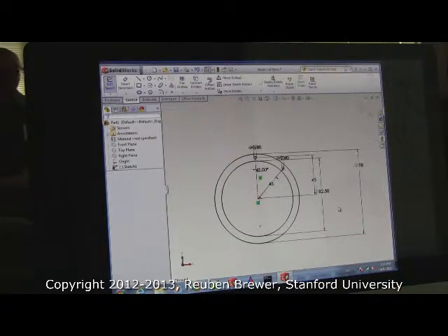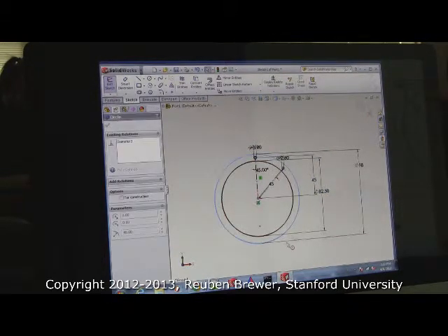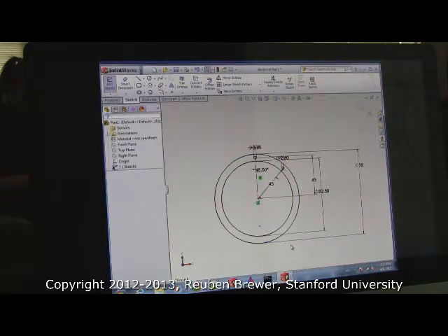So basically I'm going to pattern these all the way around here, but I'm lazy. I could just draw a whole bunch of lines, but later on, in the next lab we'll be doing stuff like 100 teeth on a belt pulley. That'll be a lot of lines. So instead we're going to do an angular pattern.